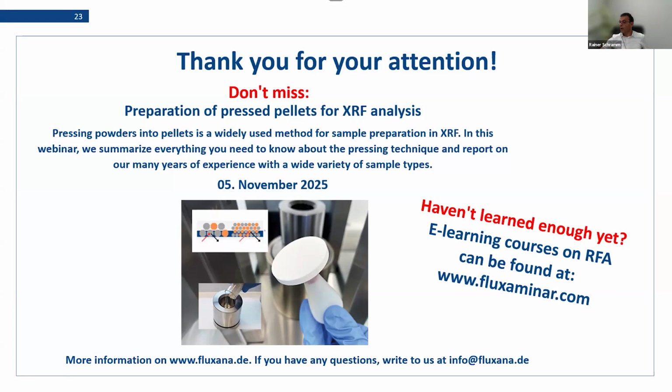Next question. How can I perform this drift correction with the same approach? Yeah, perform means then you measure, you start then the drift correction measuring program. And then, for example, you have set up 6 samples. You have to put them on the autosampler and then to perform it. And then always you get a report, and the report is telling you how much drift was really detected and how much drift correction was performed.